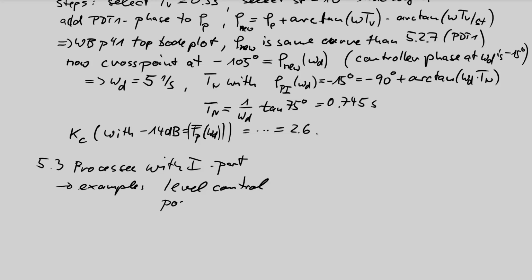The same is with position control system. In a position control system, we have a motor, say a motor with a speed, and this motor is connected, let's assume, with a belt to a second axis, and then here you can fix something on this belt, and then this movement x is integrating of n dt.